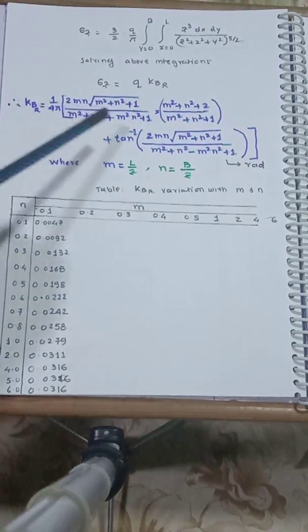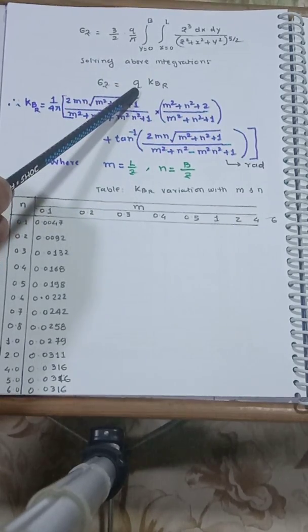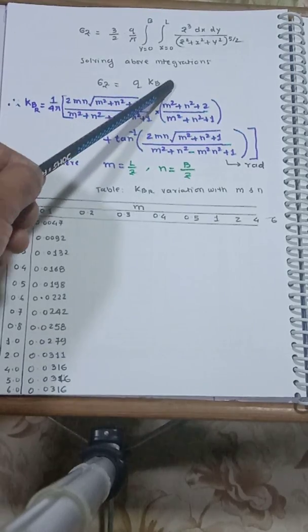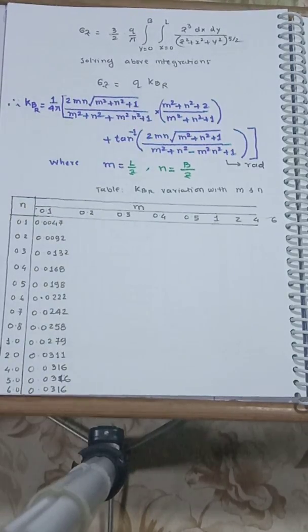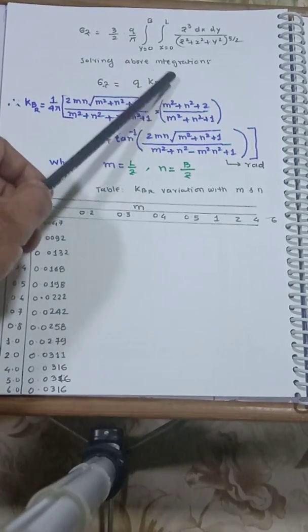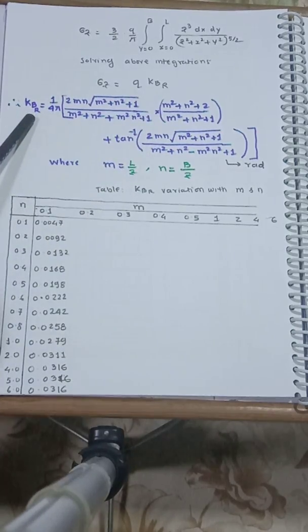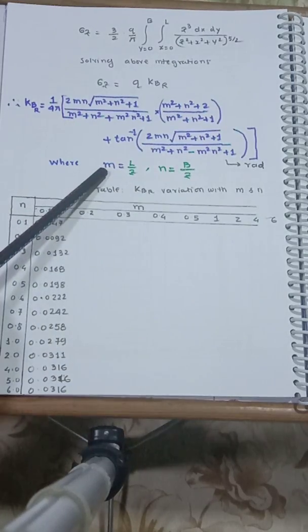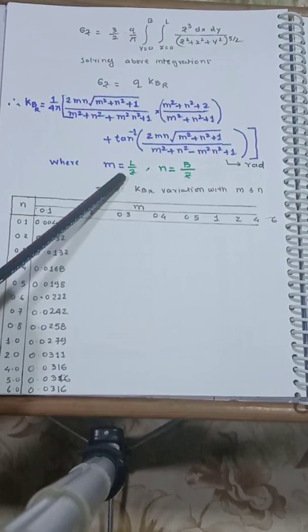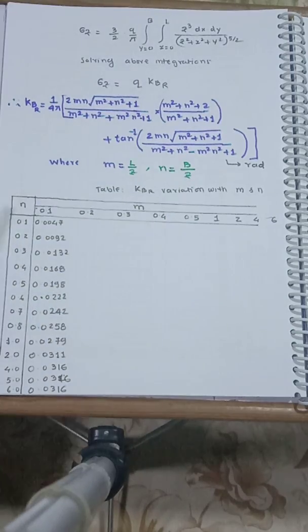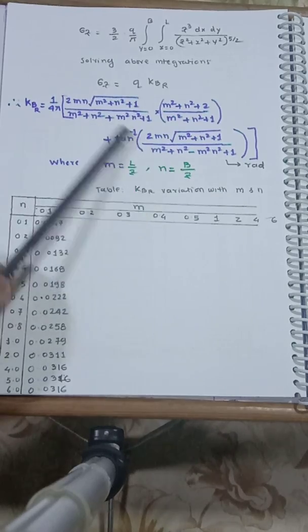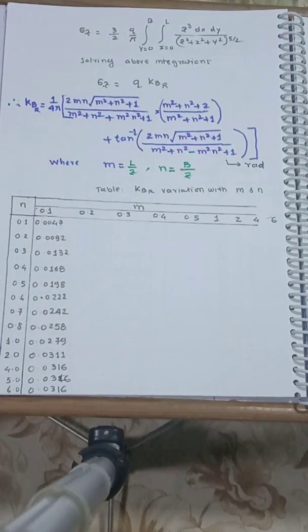Whatever result we get is in terms of the stress transfer, that is, at a rough level, an influence factor. I put R just to indicate it is for the rectangular footing. In the final result, this influence factor expression can be written in a big form. You'll find there are M and N. What is M? It is L by Z, length upon Z, and what is N? B by Z. Using these two dimensionless factors, the expression is derived.